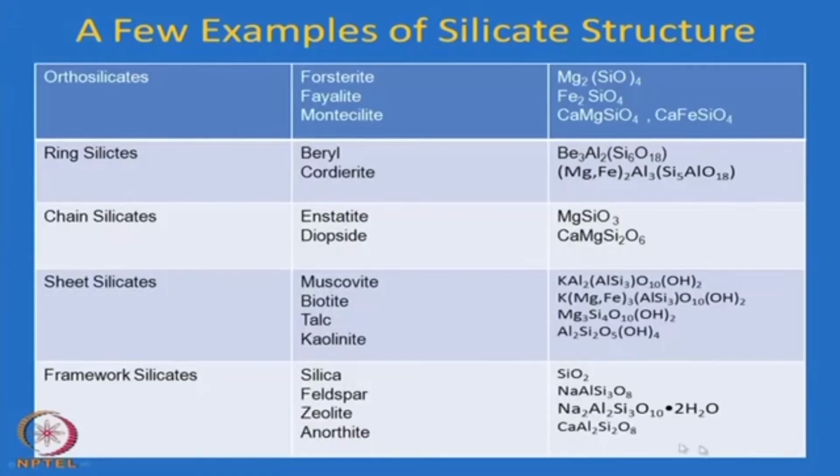It has a relatively low melting point and acts as a flux, forms a viscous liquid or viscous glass that acts as a binder for the other ceramic particles, particularly quartz and mullite and so on. So, feldspar is a very important ingredient of the whiteware family of porcelain ceramics.